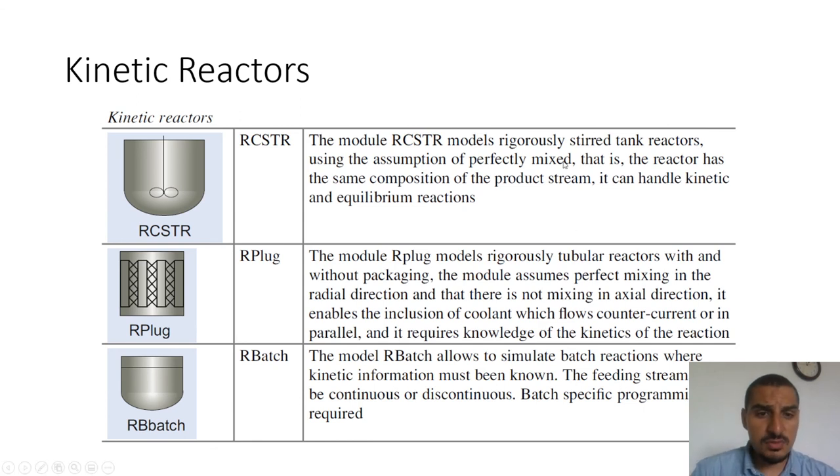It's based on the assumption of perfect mixing. This is what we mentioned before. The reactor has the same composition as the product stream. Again, we mentioned this. It can handle kinetic and equilibrium reactions, and we will talk about the reactions later. And this is the rigorous tubular reactor, the RPlug, with or without packing. So in this case, you can assume that there is a catalyst or not, based on what you need.